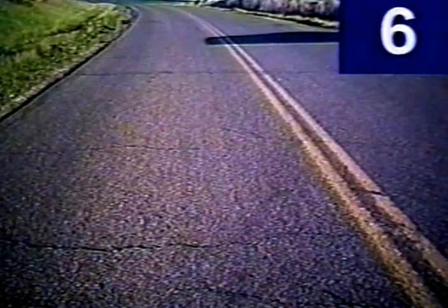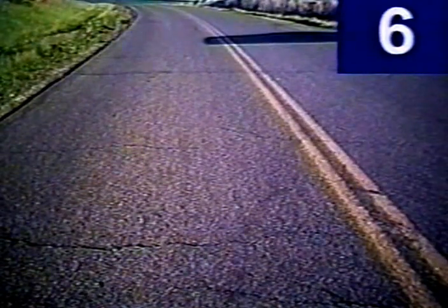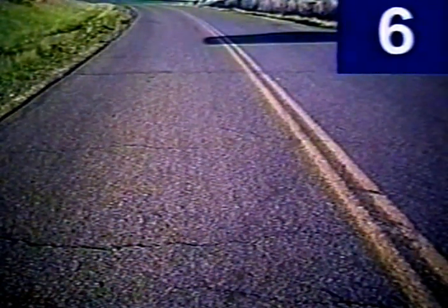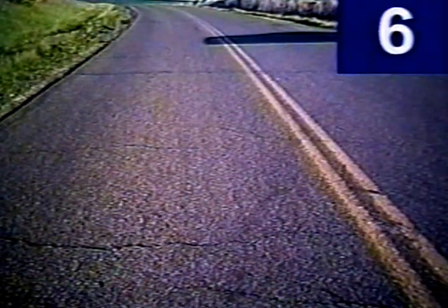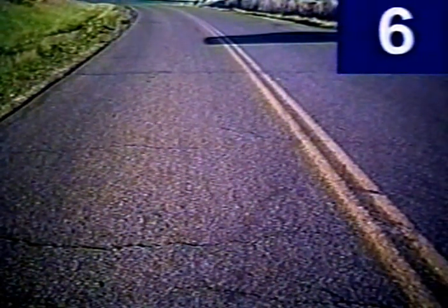Next, I'd like to move on and discuss pavements that we would rate in category 6. A pavement that's rated a 6 is one that would be a candidate for preventive maintenance treatments like surface treatments. Here we have an example of a pavement that has the first signs of raveling. You can see the rough texture starting to develop, and the fine hairline cracks are in the pavement, and now they're closer together. They're probably less than 10 feet apart. Excellent time to do a preventive maintenance like a surface treatment.